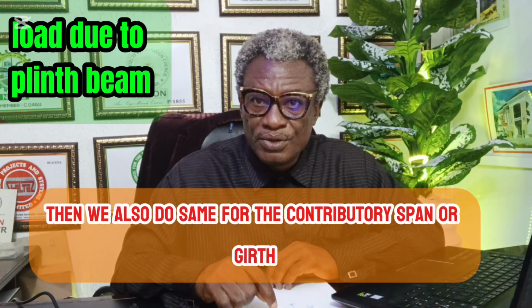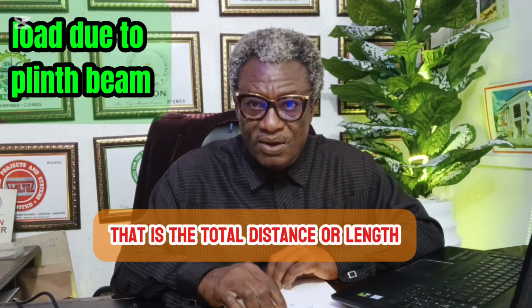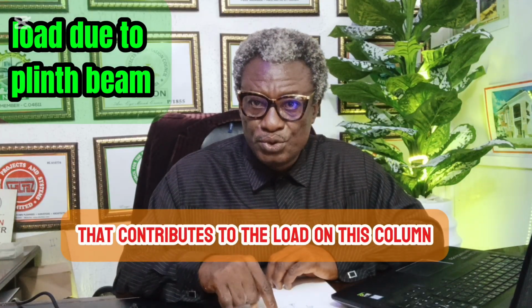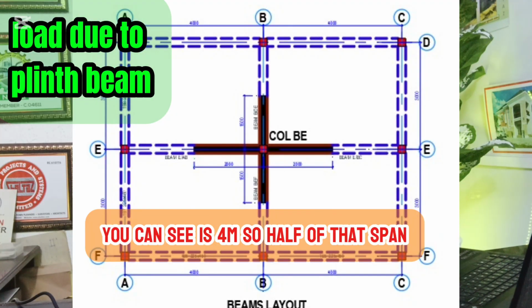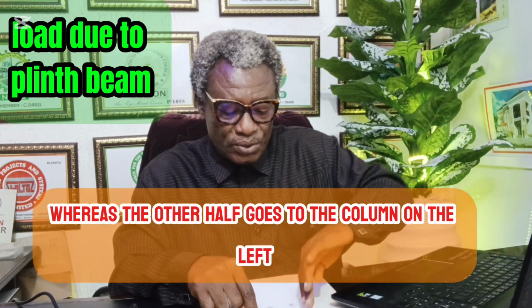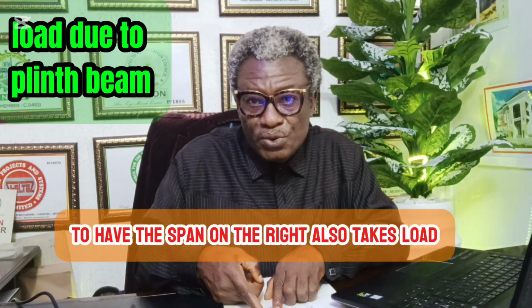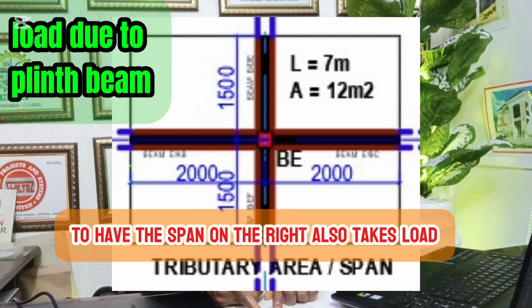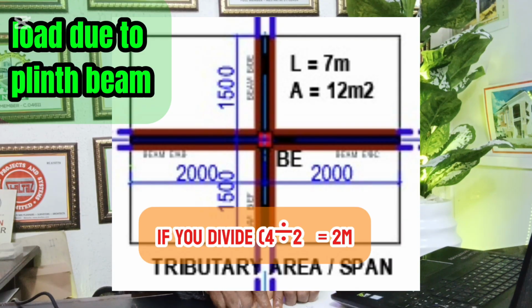Then we'll do the same for the contributory span or girth. That's the total distance or length that contributes to the load on this column. Now, span AB, you can see is 4 meters. So half of that span takes load to this column, whereas the other half goes to the column on the left. Then from that column, the span on the right also takes load. So this span is 4 meters. If you divide 4 meters by 2, you have 2. The same thing this way.